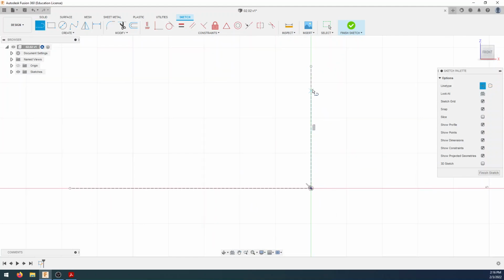So here, this is that center line. Here is that line that I'm going to eventually mirror over. So then what I'm going to do is I'm going to make sure that my line is selected, and I'm going to turn off my construction line. We know that it's a construction line when we're drawing, when we see a bunch of little dashes, and an object line is going to be nice and solid for us.